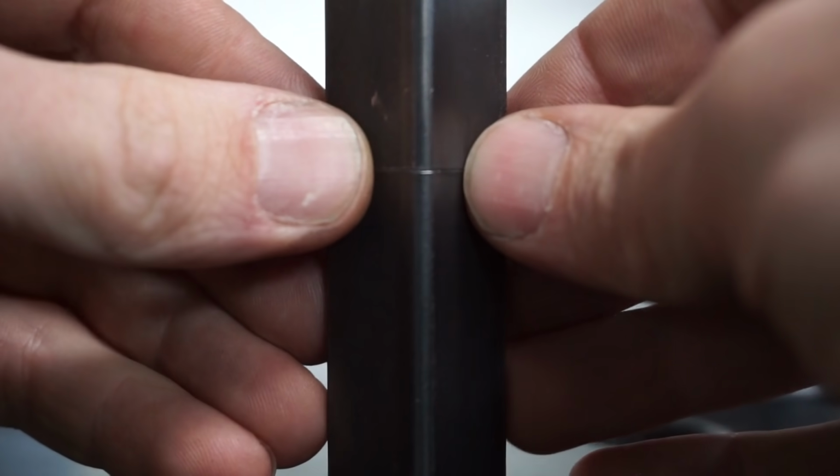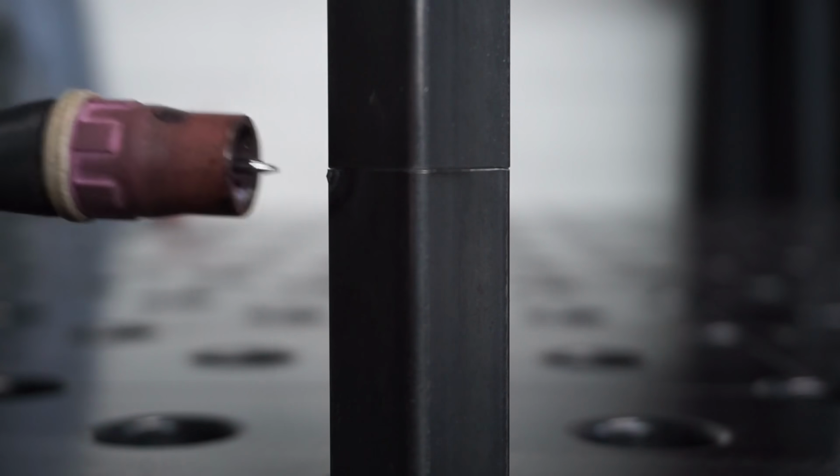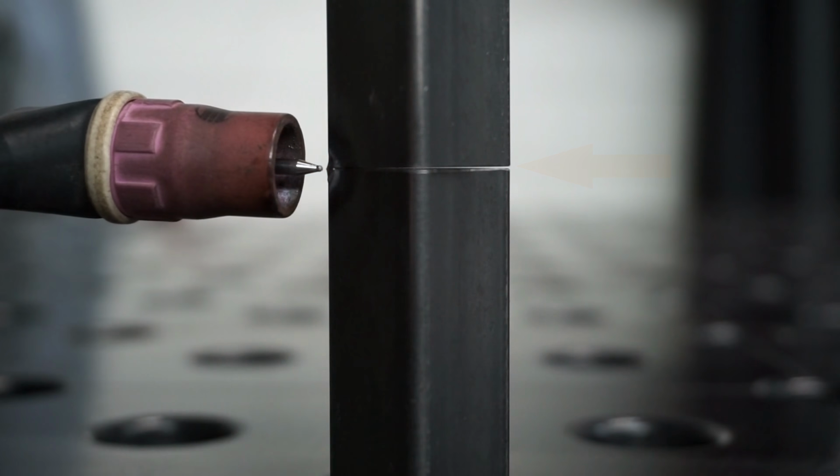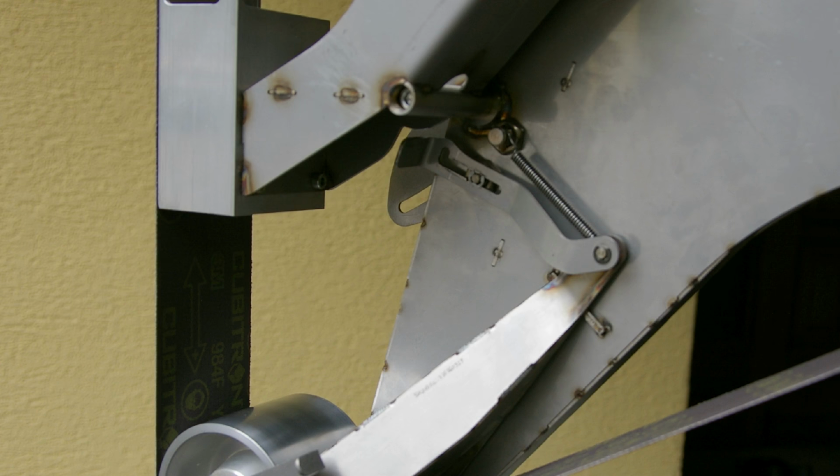And as soon as the first tack has cooled, you see that it contracted quite freely and opened up a gap. This is commonly prevented by either clamping, fixturing, or a neat workpiece design in which the precuts index and lock with each other. As tacking progresses, this becomes less of a problem because the assembly gets more and more rigid.